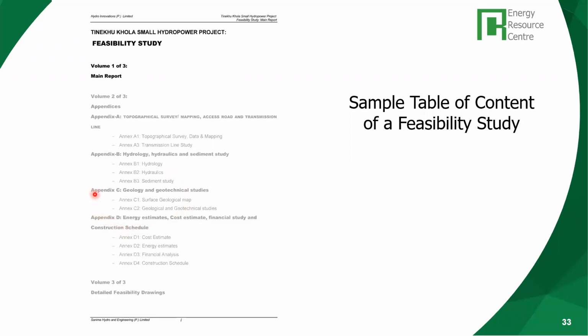Again, as I mentioned, for medium and large size hydropower projects, and small size too, a geology and geotechnical study is also very important, because if it is in a fragile environment, if the rock condition is not good, there will be settlement, there could be landslides that would damage the structures. So the geology has to be well studied. The geotechnical aspects have to be well studied. Otherwise, you have problems.